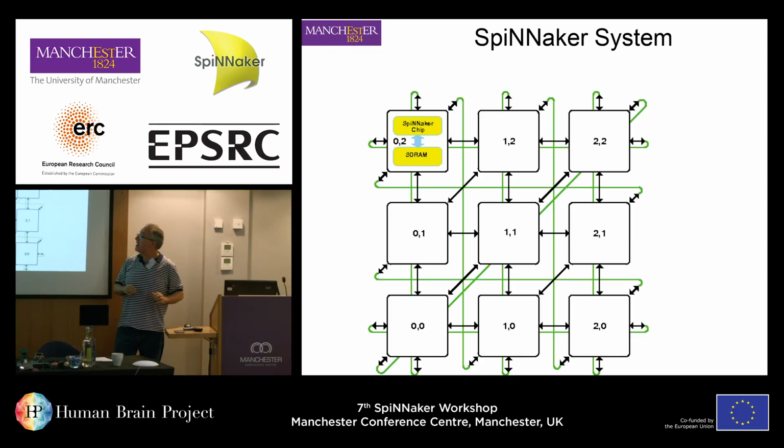This is a very stylistic overview of a section of SpiNNaker chips. Now, if you've seen the 48-node board, or even the 4-node boards in front of you, you see that there are chips and they're connected together by links. Every chip actually has 6 links. And when they connect together, they form a hexagonal grid of communication. Each of those packages, if you look on a SpiNNaker board, contains one of our SpiNNaker chips, and sitting on top of it is actually a 1 gigabit SDRAM. And that is used for storing all the synaptic connectivity information in spiking networks.